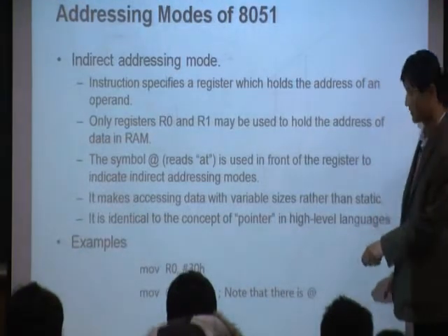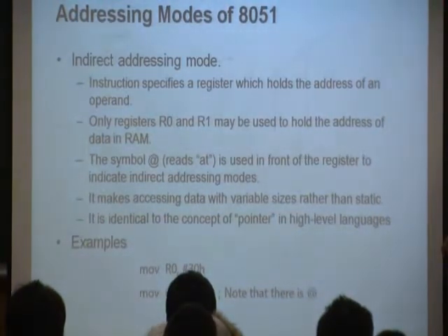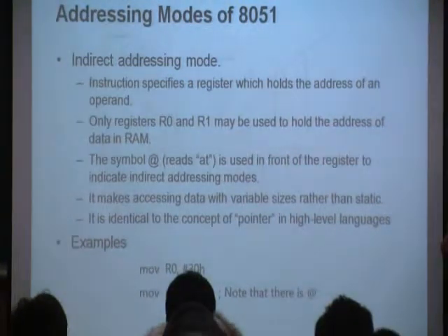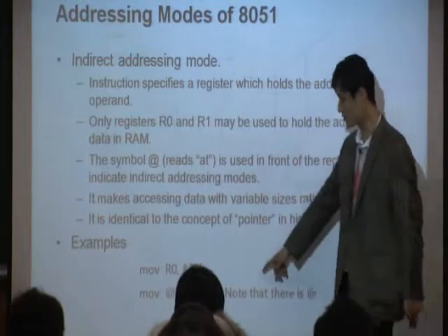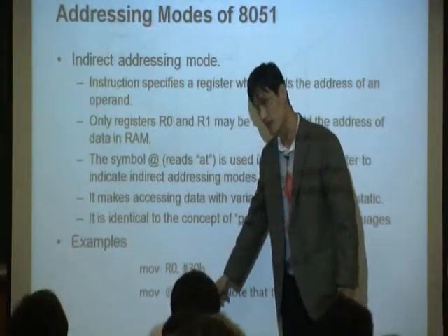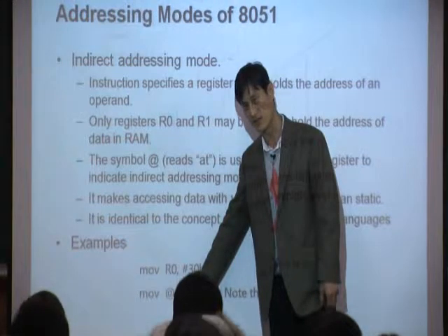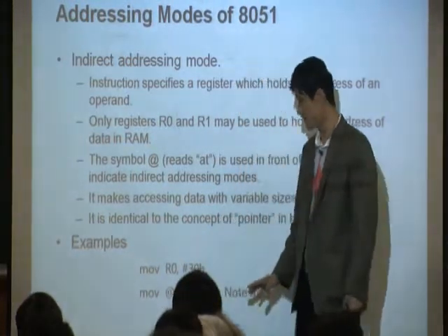So what is this 04? This is direct addressing, right? For the source address, you use direct addressing. For the destination, you use indirect addressing because we have @.